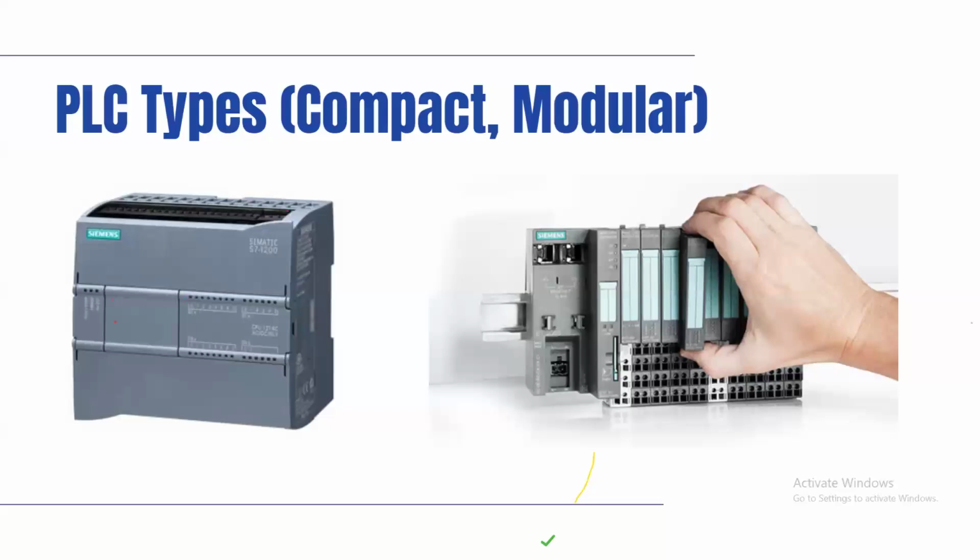There are PLCs where we can see our CPU and our IO separately. In this case, everything is fused together, so if something goes bad, then in many, many cases you have to change the entire device. Now, what I would say is that there are some PLCs that function somewhere in between.